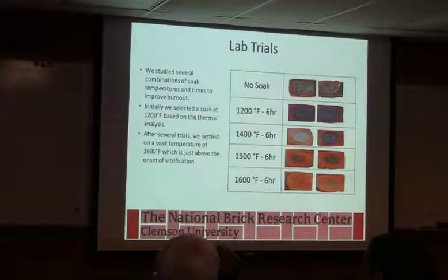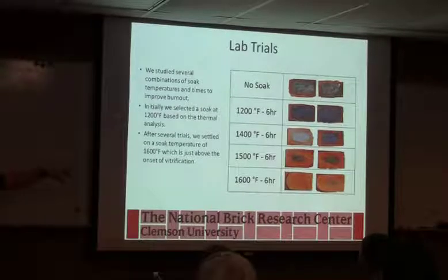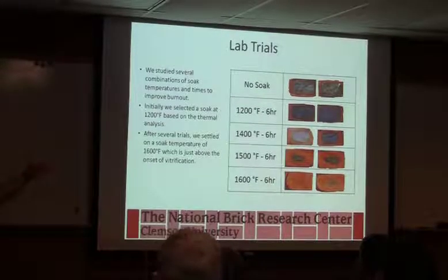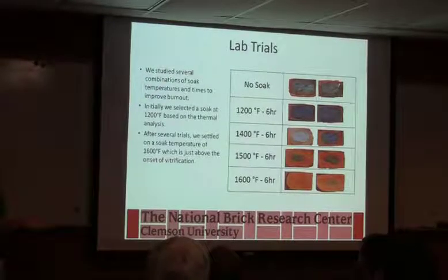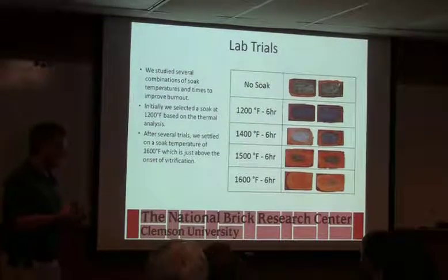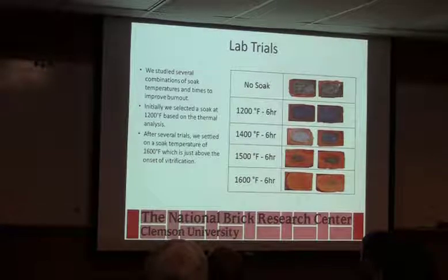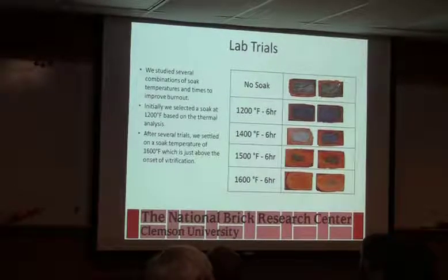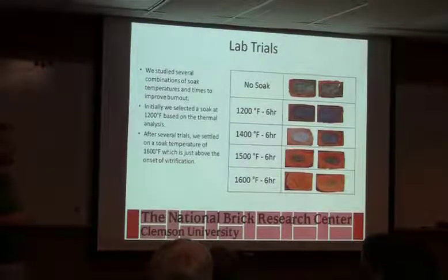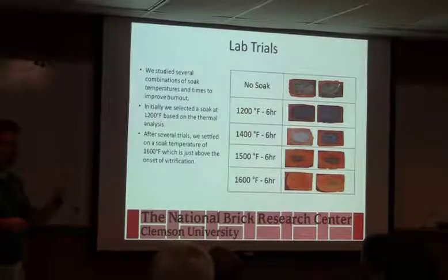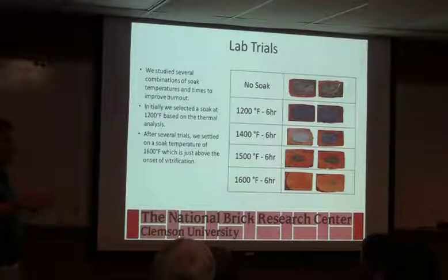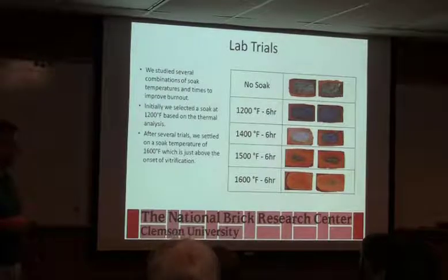It depends on your product. On this particular one, it was probably starting to seal over, but again, it depends on what materials you're using out of the mine, because that's all going to affect the temperature range. The more sodium and potassium you have in it, chemistry-wise, those all act as fluxes and actually lower the temperature of forming glasses. So depending on what the chemistry is, it will give you differences on when it actually starts to glass, when it densifies, when it does what it does. If everybody's material was the same, we'd be in the plastic industry.